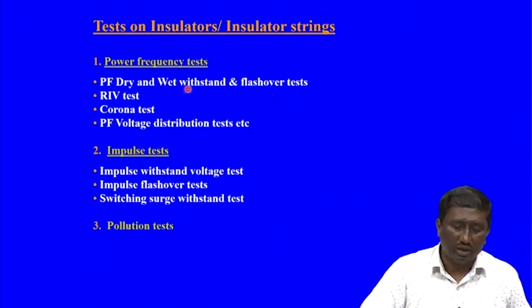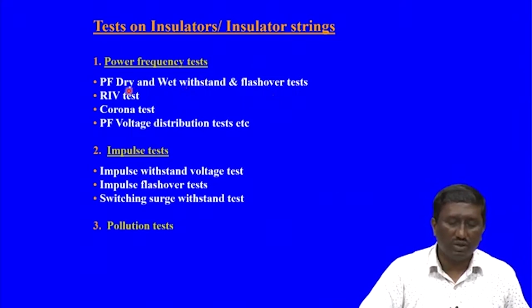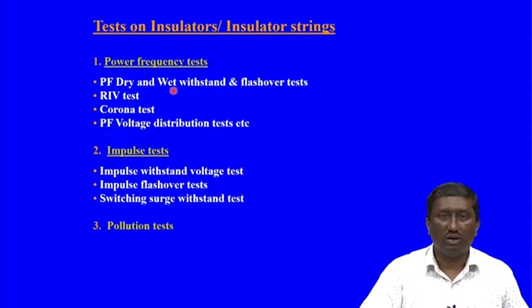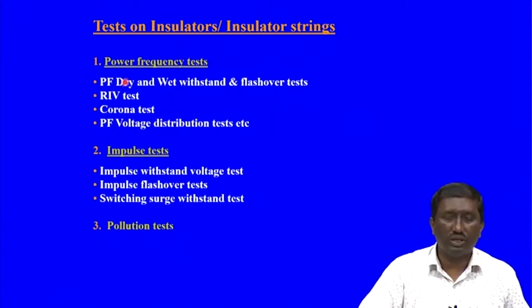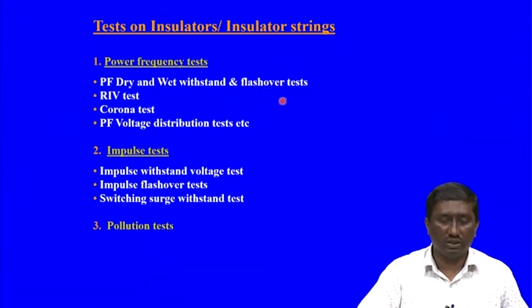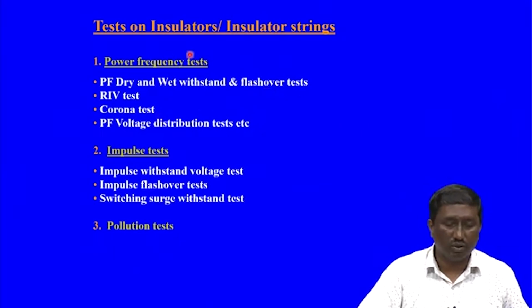So, what is the insulation withstand with normal conditions, what is the withstand level for the wet conditions in case of the rain or the surface becoming wet, and what is that flashover, what is the ultimate insulation level of that equipment, that is known as a flashover across that equipment. So, these three, that is dry, wet withstand and flashover tests are performed in case of power frequency.